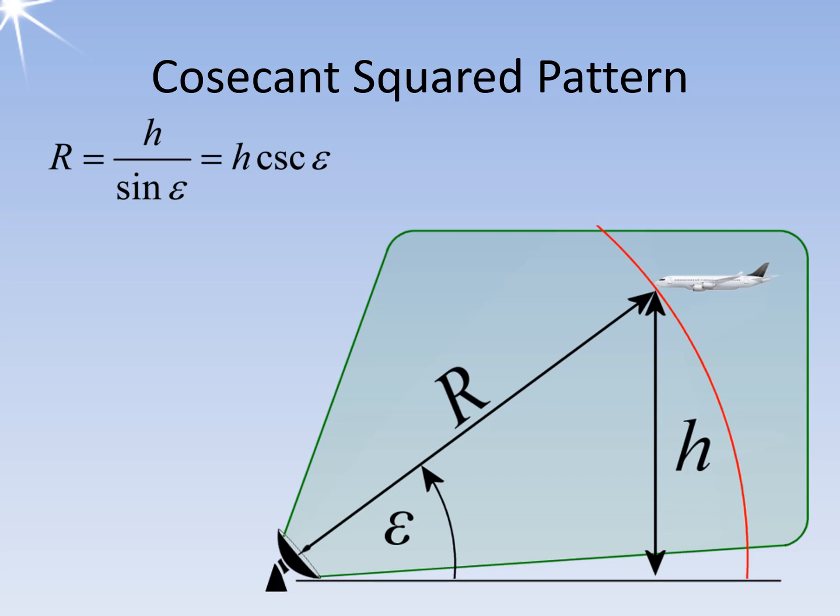It is therefore particularly suitable for air traffic control and air defense surveillance radars. Ideally, a cosecant squared characteristic ensures that an airborne target moving towards or away from the antenna at a constant height or altitude produces an echo of constant amplitude at the receiver input.